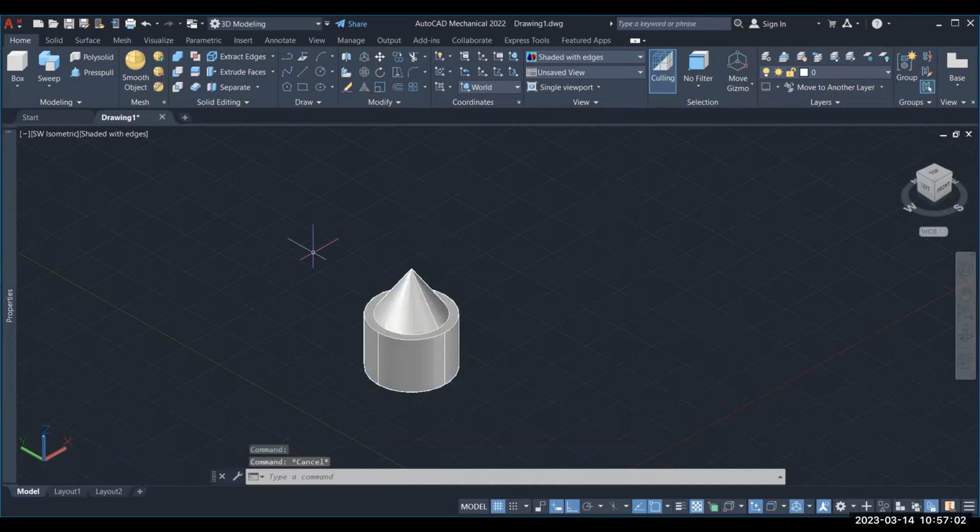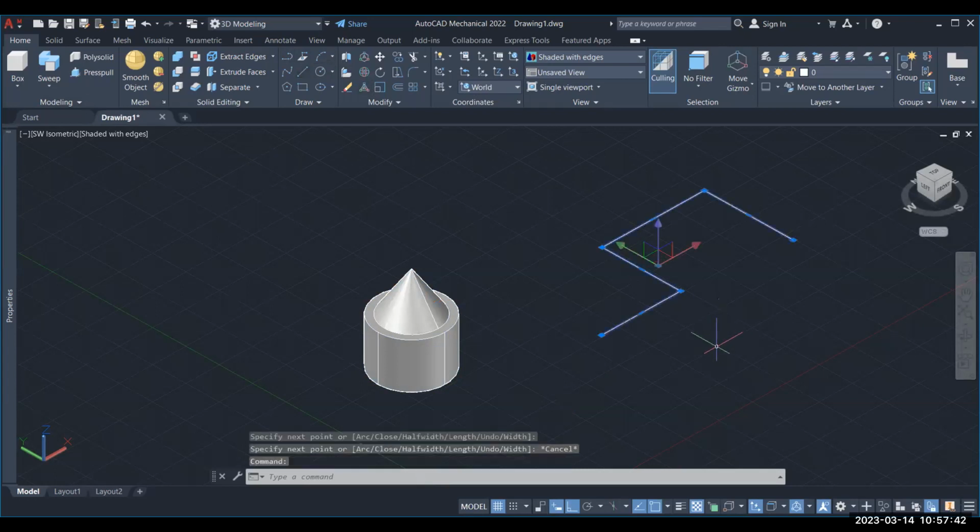And if I want to separate again, I want to make it individual objects. What will you do? I think in 2D, like a polyline has been constructed. Polyline means a combination of lines. If you want to make that polyline into individual lines, what do you do? Break or explode? Do you know explode? Like you just see now. Which option am I using? Just see, polyline. It's a single entity.